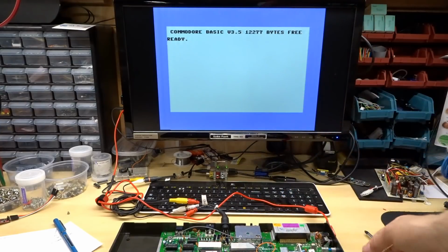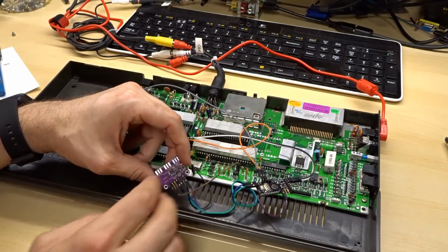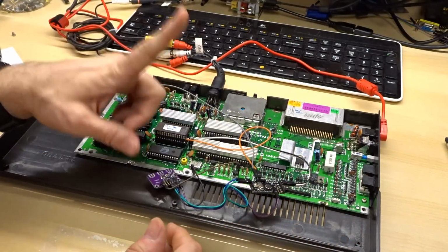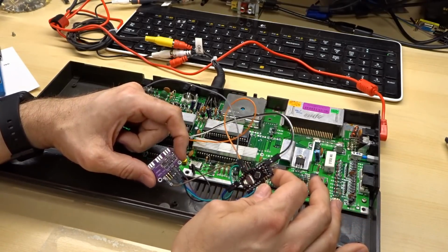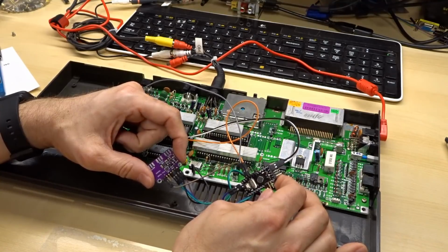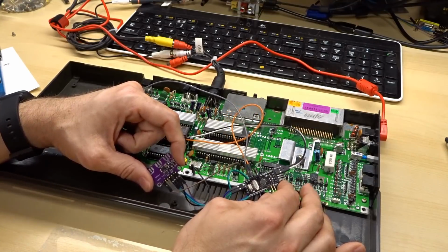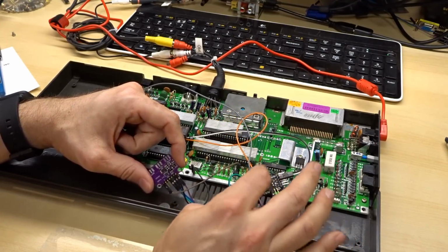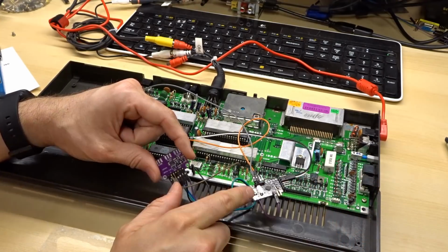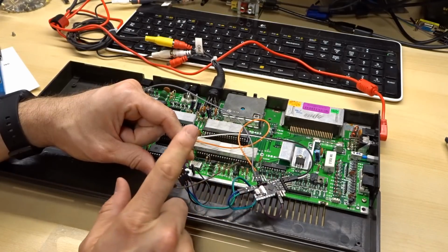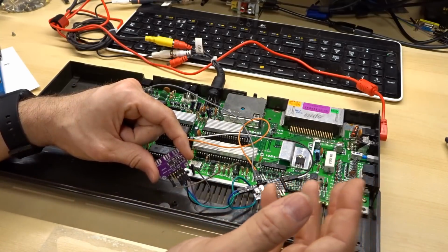So we're fully operational. Remember I mentioned a second ago that until the clock generator is programmed, it will not generate a clock, which the computer needs to run. One of the issues is the normal bootloader that's on an Arduino takes quite a while to actually start up. A microcontroller like the Arduino couldn't start instantly, or nearly instantly. The regular bootloader is kind of checking for reset signals or whatever. I don't know what it's doing, but it takes about a second or two before it does anything. At the minimum, when the Arduino boots up, it will take a second or two to program this. And that's unfortunate. The computer will just sit there and not do anything.